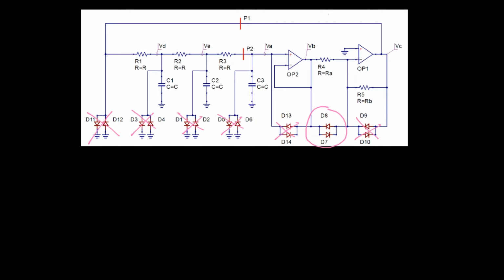Well, we know, because this is an operational amplifier, that the node right over here is always going to be grounded, because the positive terminal is also grounded. So because this negative terminal is a virtual ground, the voltage drop will always be from this node to the negative terminal. And that drop can indeed be both positive or negative. That means that diode D7 or D8 can indeed start to conduct. And what happens when one of these diodes starts to conduct? It's given that these will then behave as a voltage source with a drop of 0.7 volts.